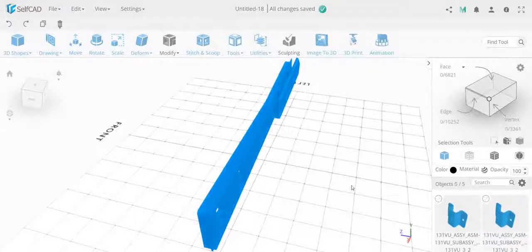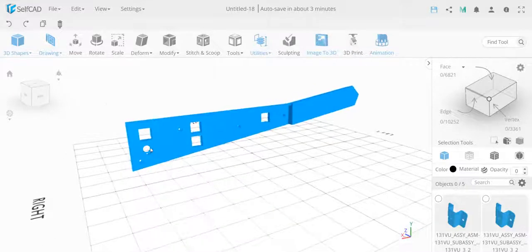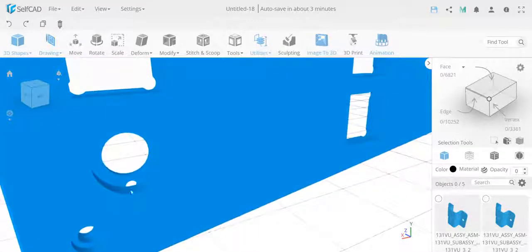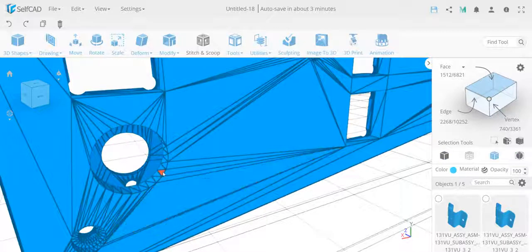I'm going to deselect everything, just click on the grid. Now I'm going to select one part. So suppose I want to reshape this particular section over here, and I want to select this entire thing to reshape. So I need to first click on the object to select it, and now I'm going to go to my face mode. But before, you can see over here, this is made of triangles. If you look at it in this mode, you can see this has a lot of triangles, the way this was created. And triangles we can't loop select. I'm trying to loop select. You can only loop select quads.